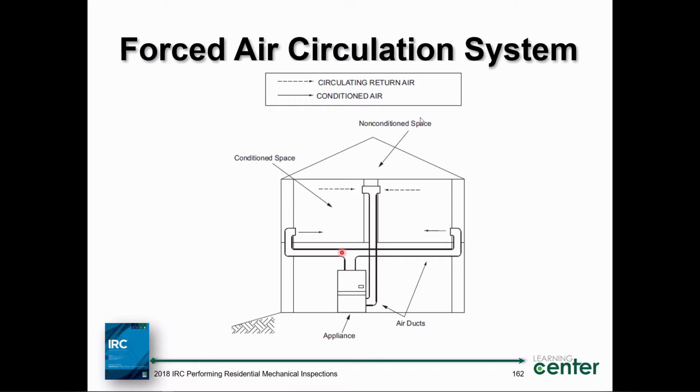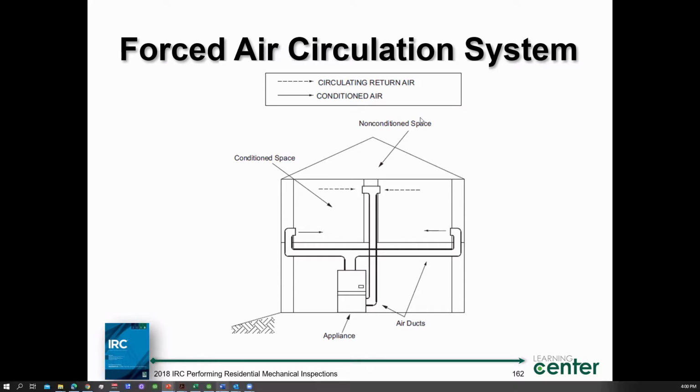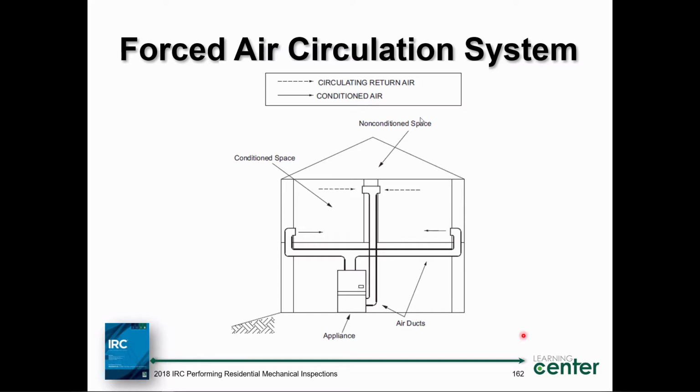It gives you reference standards. It references the ACCA Manual J for the heat loss and heat gain calculations, and it references ACCA Manual D for duct design, or an approved source, like maybe Carrier or Trane has a program that you can design the ducts to. You can even do calculations to design the duct, like prescriptive tables like we did for the gas piping. So it's kind of lacking a prescriptive way to size duct, but that's okay. You're given reference standards to do that accordingly.